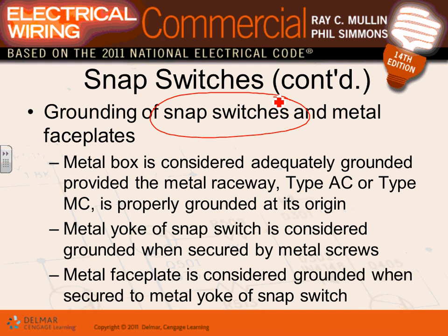The NEC code book came with a major change that you didn't care about at the time. Now you're a professional in the electrical field, you have to. They're telling you every switch has to be grounded. In the past, they used to have switches without a grounding slot or terminal. Now every switch has to be grounded.